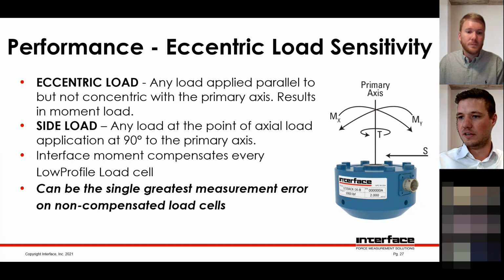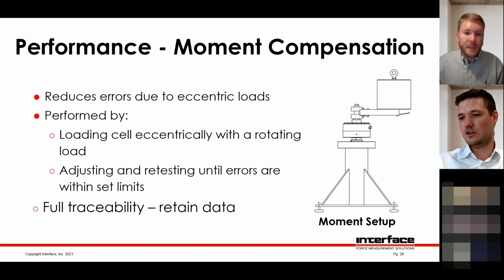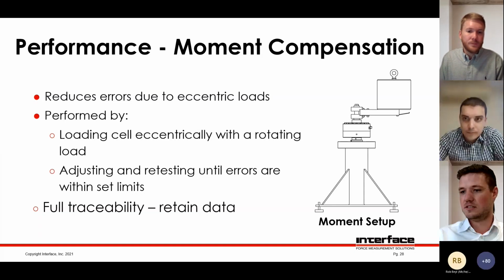So on the next slide, we'll see Interface actually do moment compensation on the load profiles. Big on the right there is an off-axis load application. So there's a weight on an arm which applies the bending moment to the load cell. Through a very manual and iterative process, the off-axis load is applied, and then adjustments are made to the load cell output. That arm swings around 360 degrees and applies that off-axis load at various points. Adjustments are made, recorded, more load is applied, adjustments are made, and so on, until it meets the spec on the data sheet.